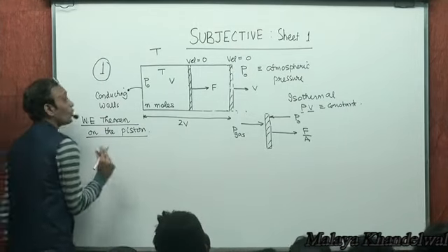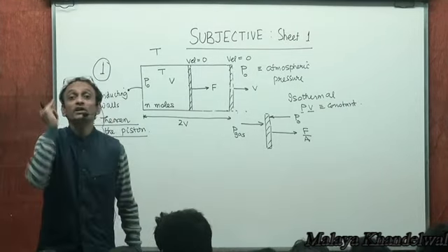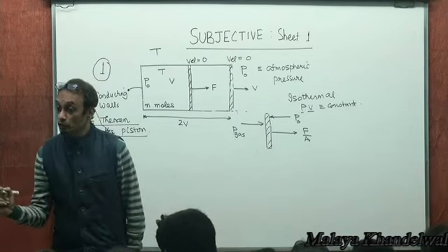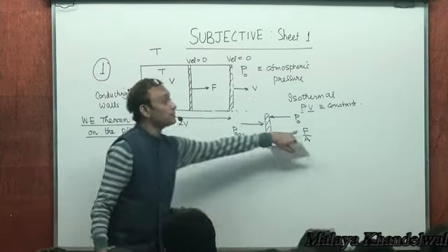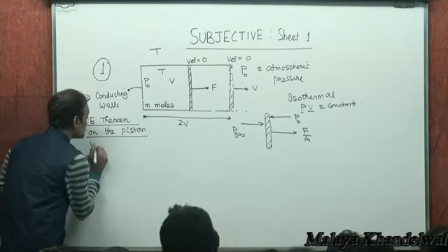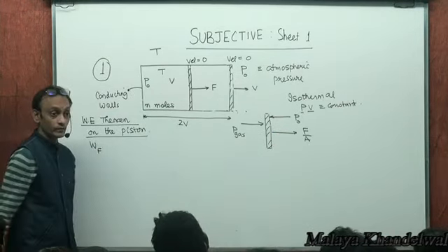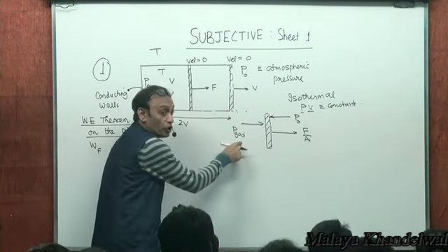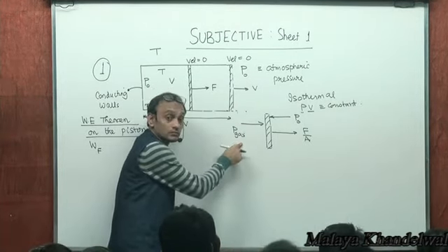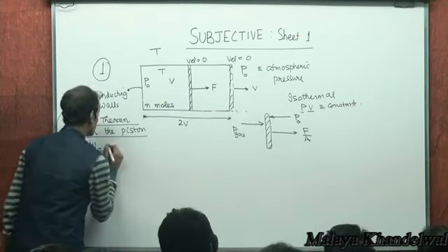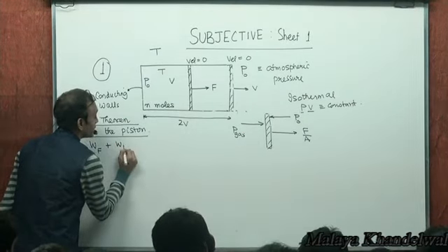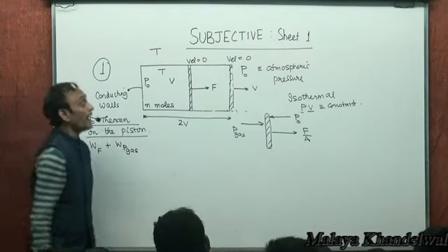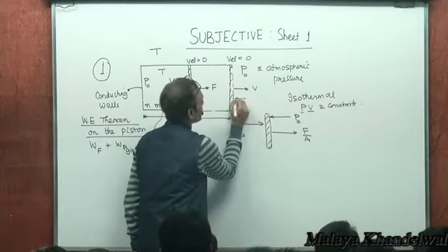What are the three things doing work on it? The work done by the external force, which we are seeking to find. Work done by the force exerted by the pressure of the gas, and the atmospheric pressure acting this way.